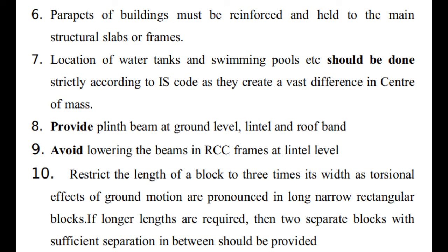Point number 7, location of water tank and the swimming pools should be done strictly according to the IS code, because they create a vast difference in the center of mass while you are creating a water body, correct? Point number 8, provide plinth beam at the ground level, lintel and the roof band. Point number 9, avoid lowering the beams in RCC frames at the lintel level.